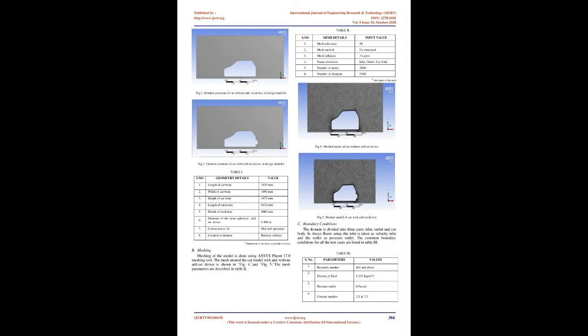Also, with a suitable and efficient downforce device such as this, the self-weight of the vehicle can conveniently be reduced without consequence, and this will compensate for the increased drag in terms of fuel consumption. Shyam P. Kodali and Srinivas Bezaveda [5] explained that due to the disturbance created in the streamline flow by the presence of a rear spoiler, there is a reduction in the flow separation at the trunk, resulting in an increase of turbulence. In conclusion, their study reveals that rear spoilers have a considerable effect on lift, i.e.